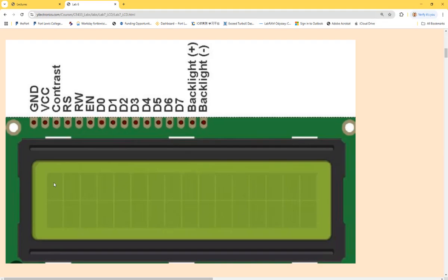And also 1-line display or 2-line display. You can see you are able to display 2 lines. It's a 16 by 2 display module. But if you don't want to display anything on the second line, you can set it up as just 1-line display. In that case, you need to write an instruction to it first before you write the data to it. And there's only one parallel data channel, 8 bits, so this one is being used as instruction and data at the same time.